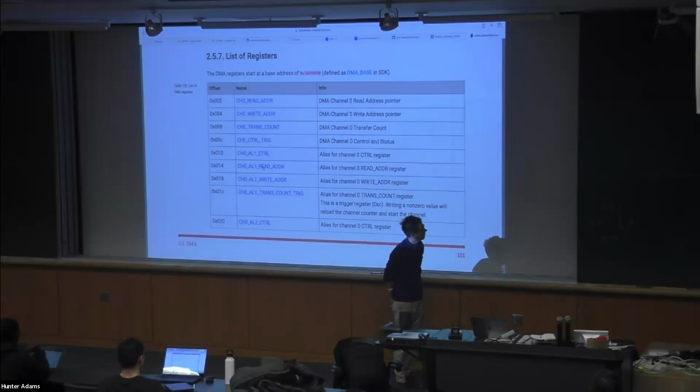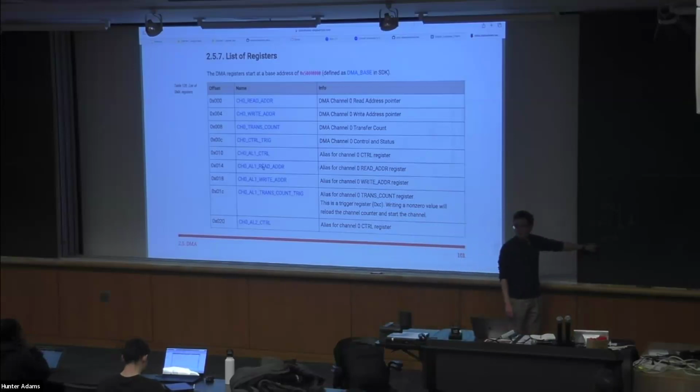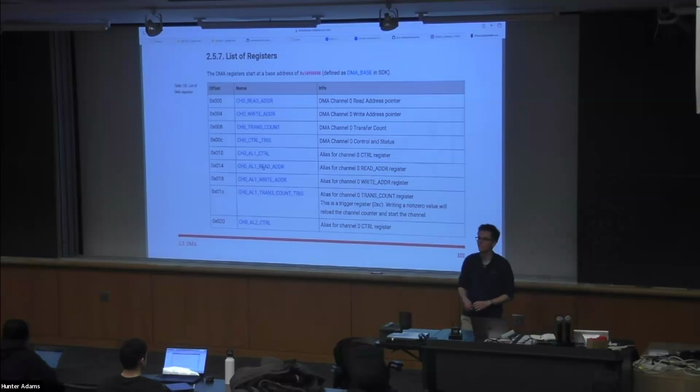Yes? Is there any reason why we can't delete the other chain? No, that would be fine. As long as, to start, this is set to the correct read address, then if you delete this chain and keep this one, the first time you trigger it, data will send out the sine wave, trigger the control channel, which rewrites its read address but doesn't start it, and then the next time you start the data channel, it would be properly configured. That would be fine as well.